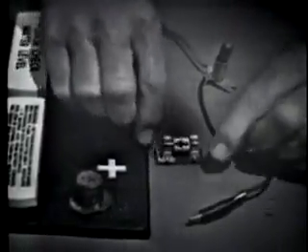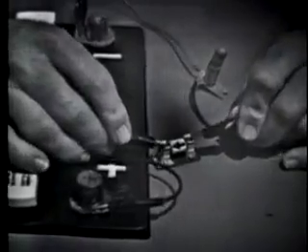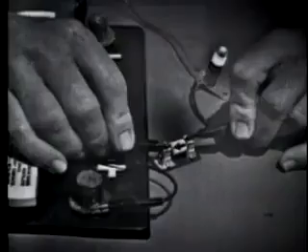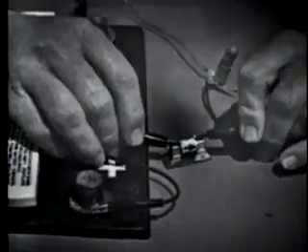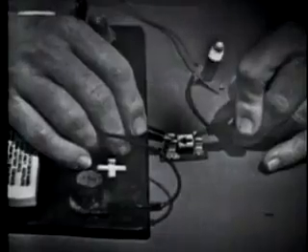Some devices will operate only when current is flowing in the proper direction. This semiconductor diode is such a device. Now, I'll make a connection here. Move the bulb in so we can see all of the action. Now, if I apply current to the device in the proper direction, like this, the bulb lights. If I turn the diode around and try to make current flow in the wrong direction, nothing happens. So to make this diode work, we would have to know the direction of current flow.